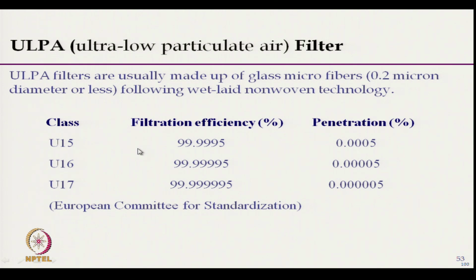They are used for fine filtration. Here glass microfibers of 0.2 micron are used, and mainly wet-laid non-woven technologies are used to manufacture ULPA filters.